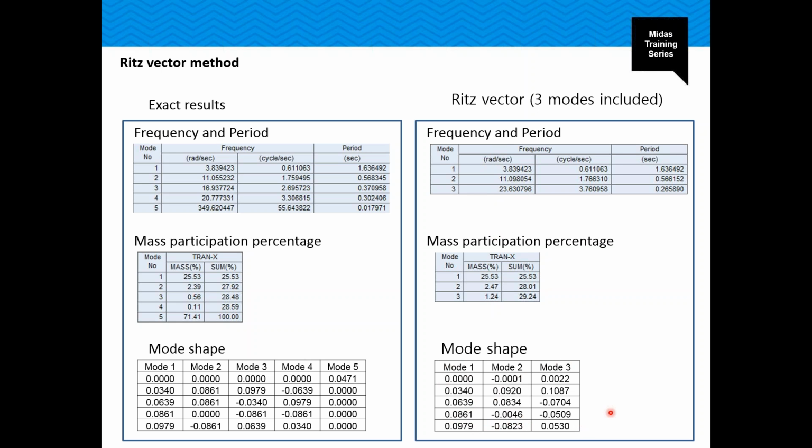The frequencies and eigenvectors are approximations to the natural vibration frequencies and modes of the system. The approximate results are generally more accurate for the lower modes and gradually deteriorate for the higher modes. Usually, the second half of the frequencies and modes is not accurate enough to be useful. Thus, the number of Ritz vectors included should be sufficient to determine accurately the desired number of natural modes.